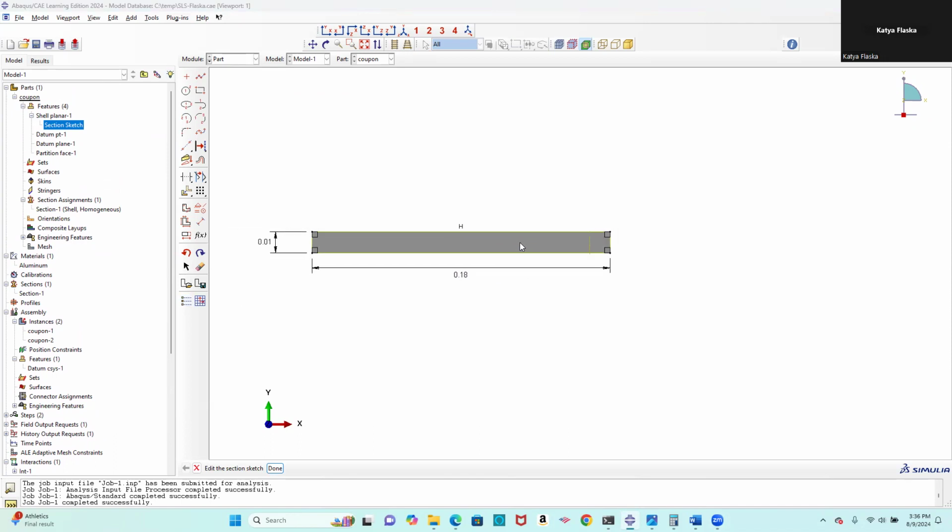Effectively, you're going to want to start with modeling your specimen geometry, which is dictated by ASTM D1002. The lap shear specimen is recommended to be 177.8 millimeters long, which in this top-down view, you can see here along the length and base units, and 25.4 millimeters wide. This is shown here on this dimension, but it's divided by 2 because at the end of this model, we're going to mirror our results in order to best maximize the amount of nodes available in the Abaqus Learning Edition.